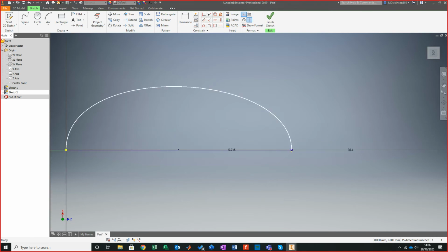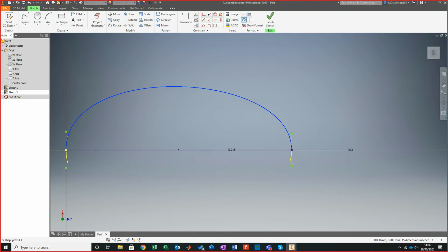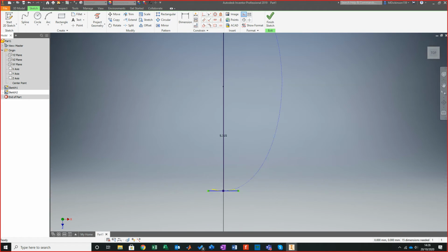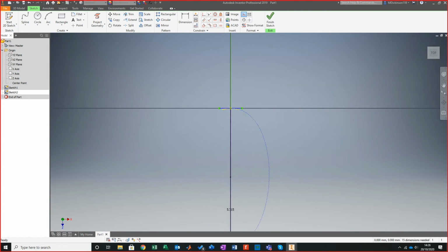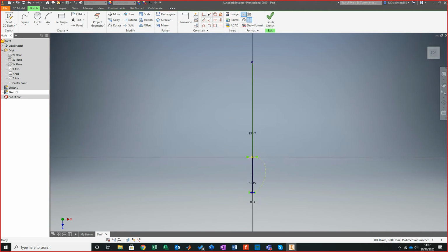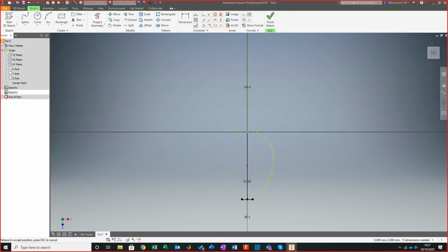So now what I want to do is left click on here, and turn that into construction lines themselves. Now this allows me to define what distance my spoon's going to sit at. So if I pull on the handle and stretch it right out, or go right in, I'll set it to something. I'm looking for the ideal egg shape, if you will. But if you don't know your dimensions to operate to, this in essence allows you to do that. But the beauty is we could dimension this.